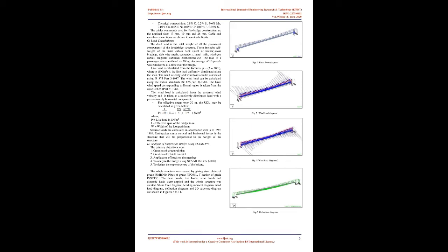Various loads and combinations are included in the frame analysis, also included lateral loads. Structural design is to be done using limit state method. Material: grade of reinforcement, Fe 415; grade of concrete, M25; density of concrete 2500 kg/m³. B. Design specifications. The preliminary design was based on the Indian Standards and Design Manual for Bridges and Structures.